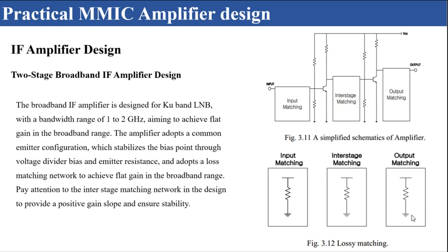Pay attention to the interstage matching network in the design to provide a positive gain slope and ensure stability, and the amplifier's schematics are shown in figure 3.11, and the most normal topology is the use of the resistors in series with matching circuits as shown in figure 3.12.